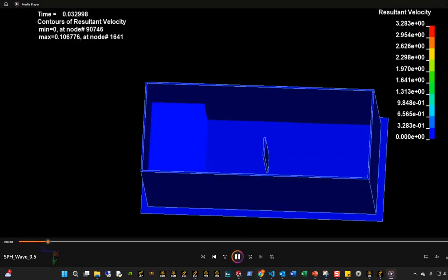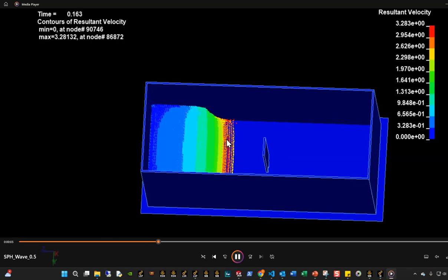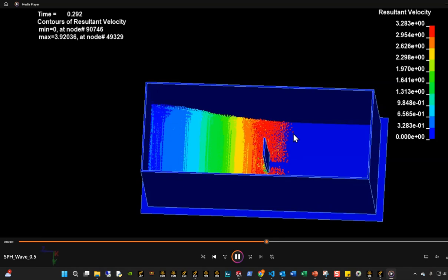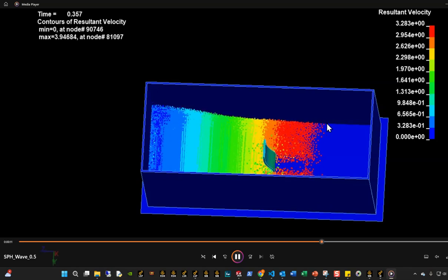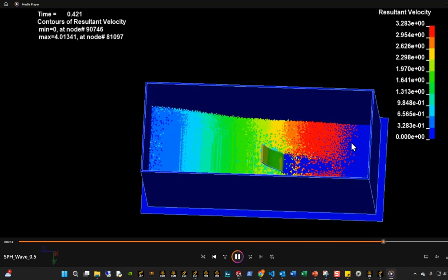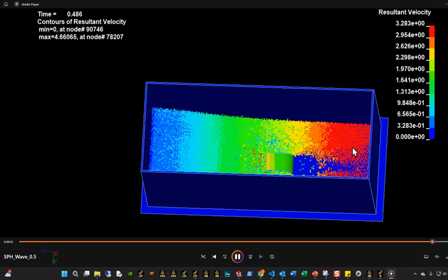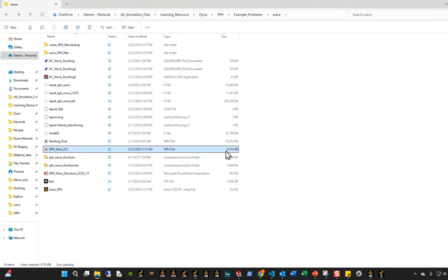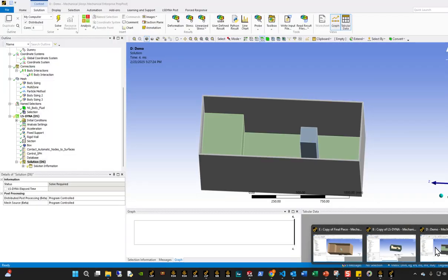If we look at something like this, you can see in this case the particle size is a lot less dense. So you can already see there are some deactivated particles right there that shouldn't be like that. Those are technically deactivated because they're too far separated from their neighbors. So that's something we want to pay attention to in terms of the behavior of SPH when we are modeling with this kind of technique.